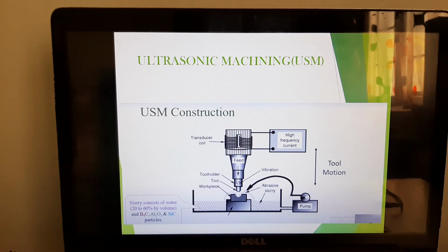All this time, you're looking at your machining, and your product would be either a solid abrasive. If you remember, in abrasive and grinding processes, we use abrasive powder, and then we rub the surface using leather in the lapping process. We did use a mandrel with embedded abrasive stones to grind the inner surface of a hole.